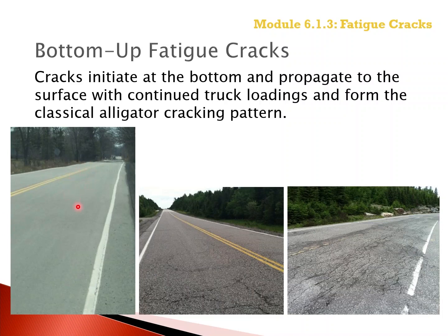With continued truck applications, the classical alligator cracking starts to appear as the longitudinal cracks start to interconnect. And then over time, with many wheel load applications, they form the more severe classical alligator cracking.